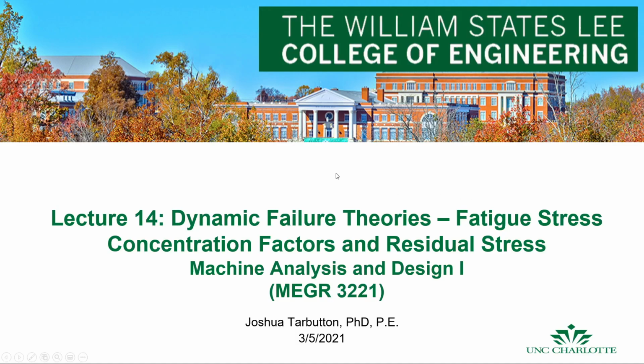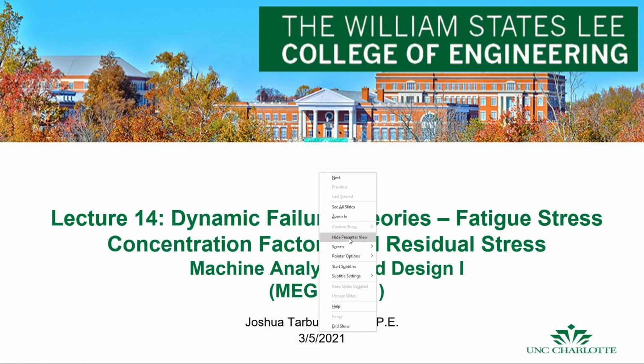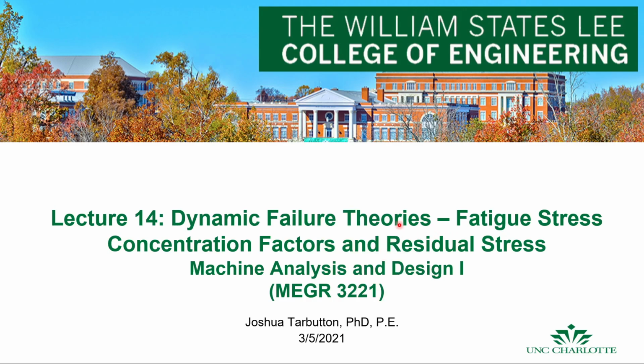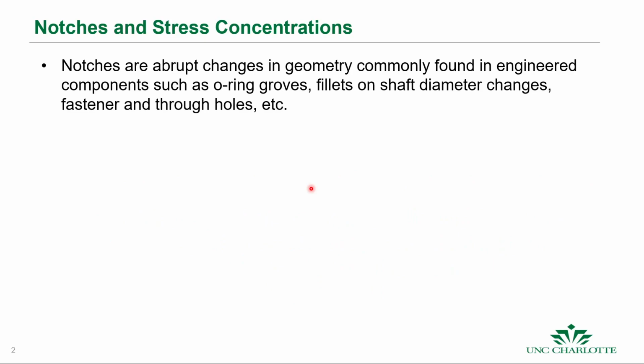All right, so today we are going to be continuing to talk about fatigue, and we're going to talk about stress concentration factors, residual stress, and then do an example of uniaxial stress. So just like we saw in the static case, if we have changes in the cross-sectional geometry, that leads to a stress concentration, shows up in things like O-rings, grooves, fillets on shaft diameter changes, and etc., including fasteners and through holes.